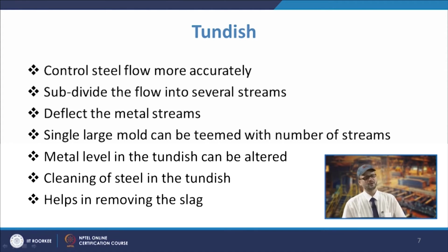Then you have also the possibility of the cleaning of steel in the tundish. Many times in the past it has been seen that the cleaning operation is also done in the tundish. Even now, we think of having the tundish act in such a manner that if there are any inclusions, they must float.